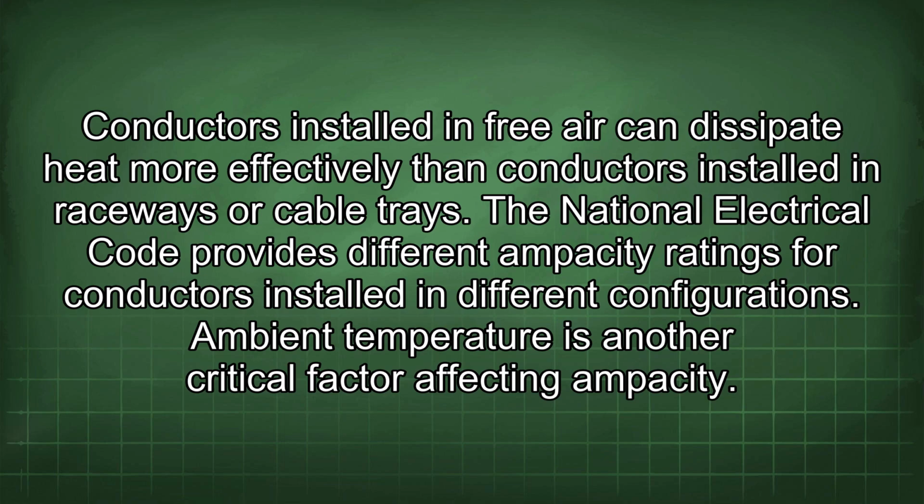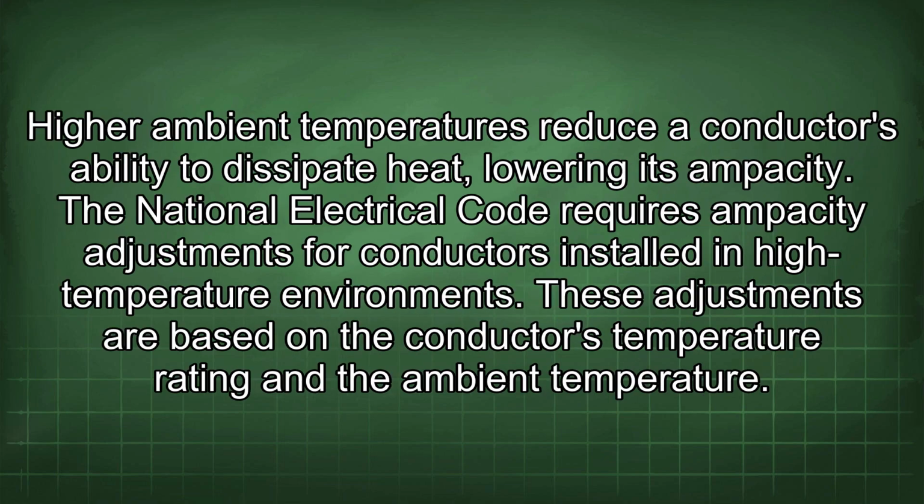Ambient temperature is another critical factor affecting ampacity. Higher ambient temperatures reduce a conductor's ability to dissipate heat, lowering its ampacity. The National Electrical Code requires ampacity adjustments for conductors installed in high-temperature environments. These adjustments are based on the conductor's temperature rating and the ambient temperature.